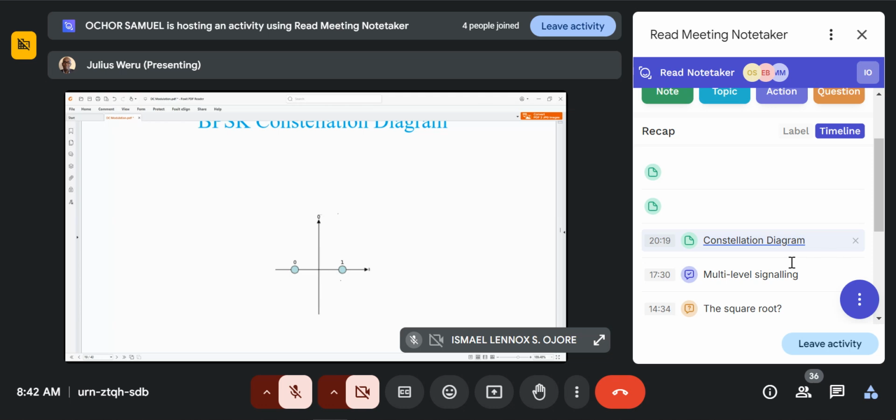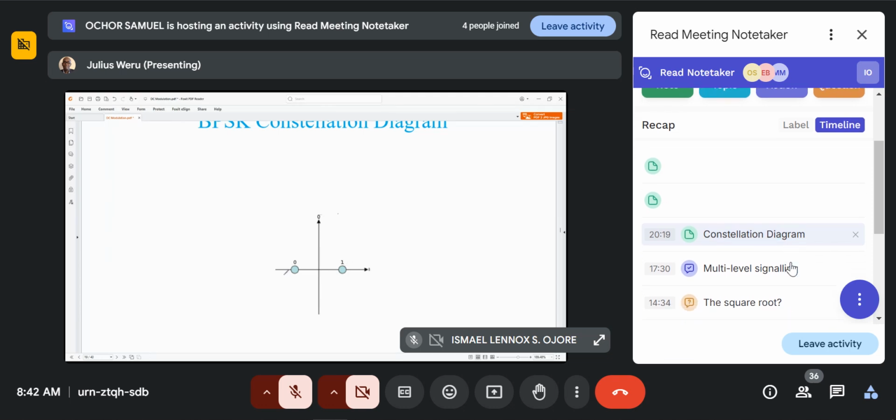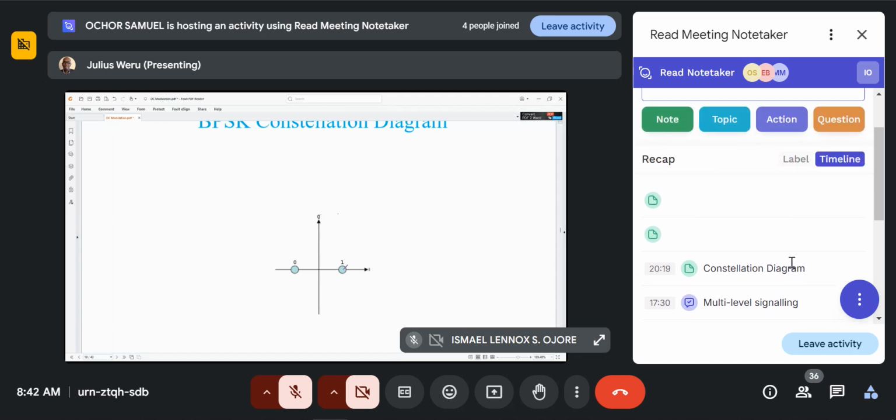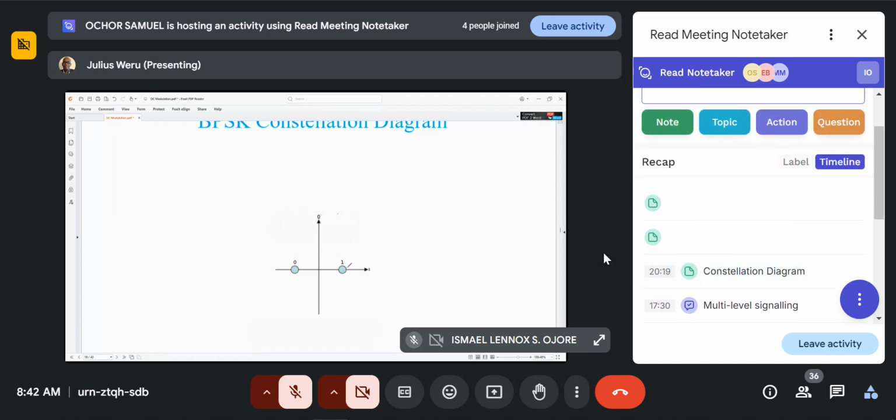Because in this case, you can see when you have 0 and pi, you have the largest Euclidean distance between 0 and 1. What it means is, to change a 1 to be received as a 0 in PSK, you have to distort the phase of this signal by 180 degrees. Well, not 180 degrees, anything above 90. If it goes above 90, then it will be considered to be a 0. So you can see you require quite a lot of phase change to get here.